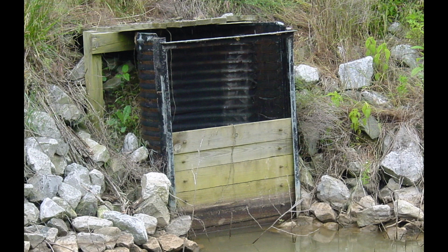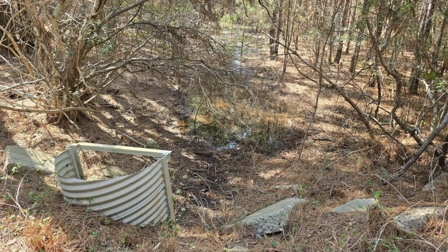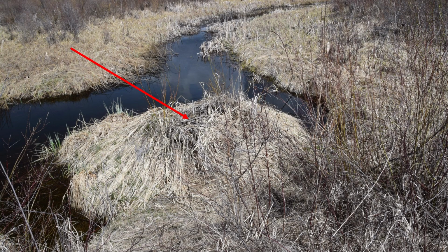When installed in a wetland or a pond that's not supplied with water from a perennial stream, the pond will often dry because of water leaking between and around the boards. Dry wetlands and ponds are common where flashboard risers have been used because they all leak. Here's where beaver filled and covered a flashboard riser with mud, sticks, and vegetation. However, they were unsuccessful in blocking water from flowing through the structure because of how badly it was leaking.